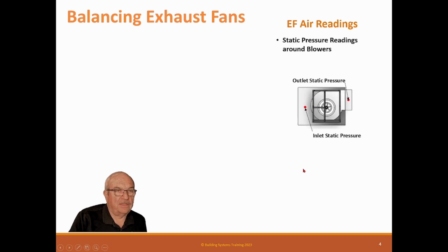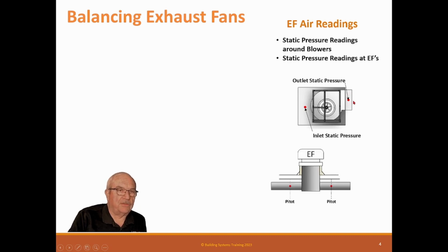Balance and exhaust fans. Okay, so this is like an inline blower, and basically what you want to do is read your static pressure right at the discharge of the fan and right at the inlet of the fan in the cabinet, because you want to read the fan curve. So you need the pressure across that fan. You can't have any device between the location where you take the pressure and the fan discharge. Now you have to understand that this fan is going to be a jet right out of there, but for static pressure readings it doesn't really matter, as long as you're not trying to read right on the edge.